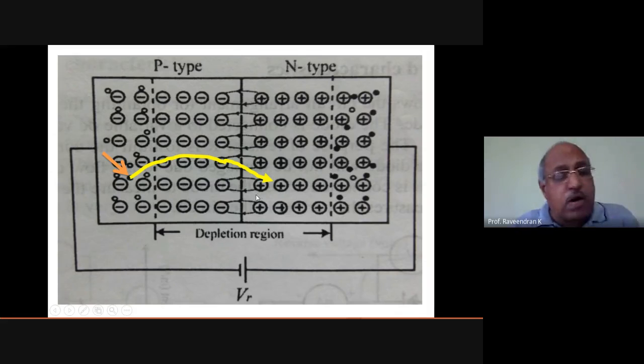That's a very small current, because under normal conditions, when the diode is forward biased, it may conduct milliamperes or even amperes of current, since that is the current flow condition. But when the diode is reverse biased, it will not conduct current through the junction.